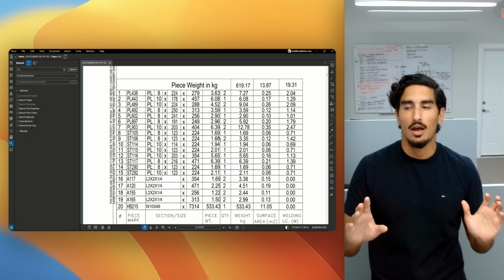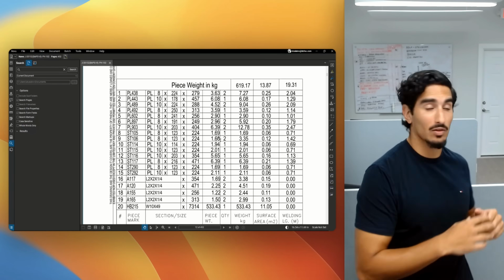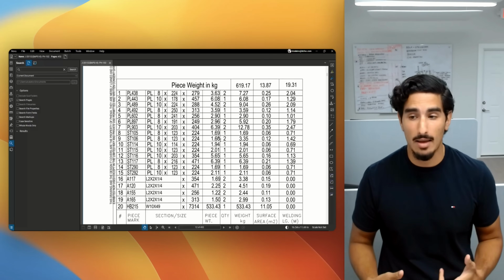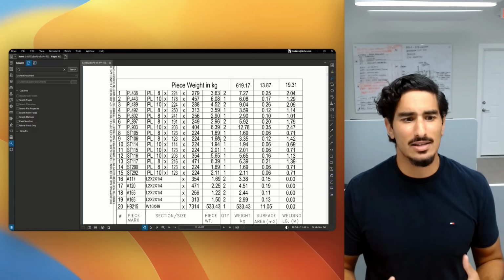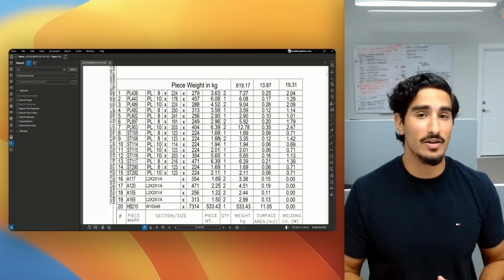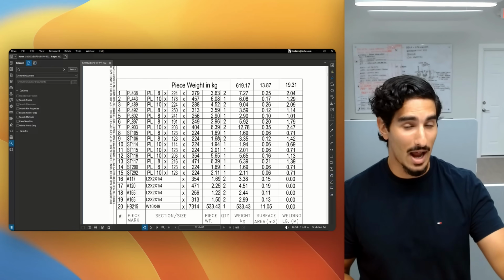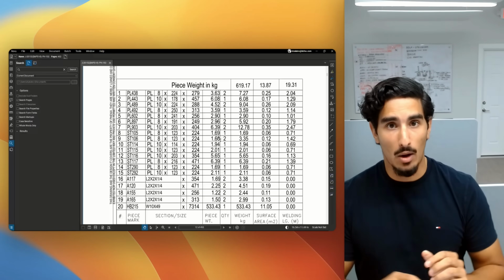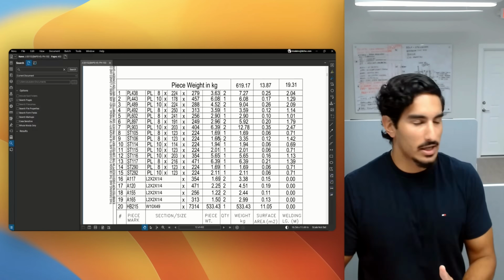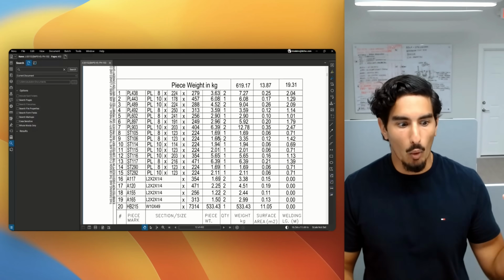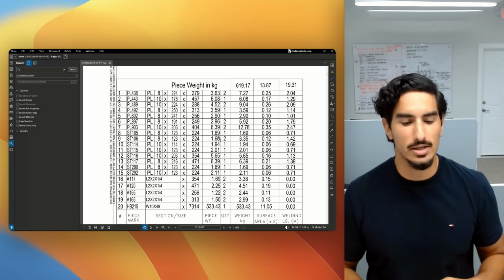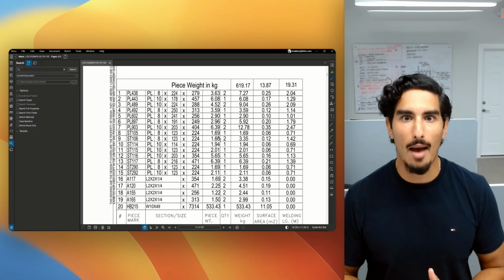And this is something that I would not do. I have asked a lot of engineers if they do that when they're reviewing shop drawings, and I haven't heard anyone yet that does this same verification process, just because it's really tedious. Typically, when I'm reading through these drawings, if I have one verification point that I am confident in, that I could populate the cell in a way that I believe to be true, I will go ahead and do that. And I won't have 2, 3, 4 different layers of redundancy in these reviews, just because these things are time sensitive. And really, I want to be able to get this done as quickly as possible to keep construction moving. So once I feel very confident about one verification system, I'll move on and make my decision and I'll be happy with that.